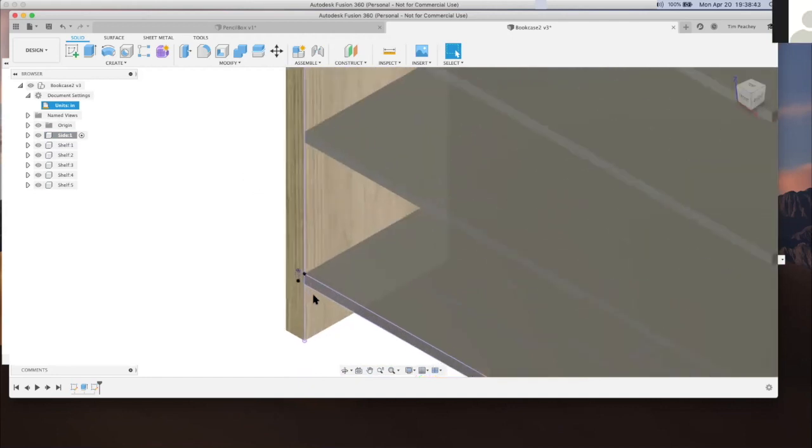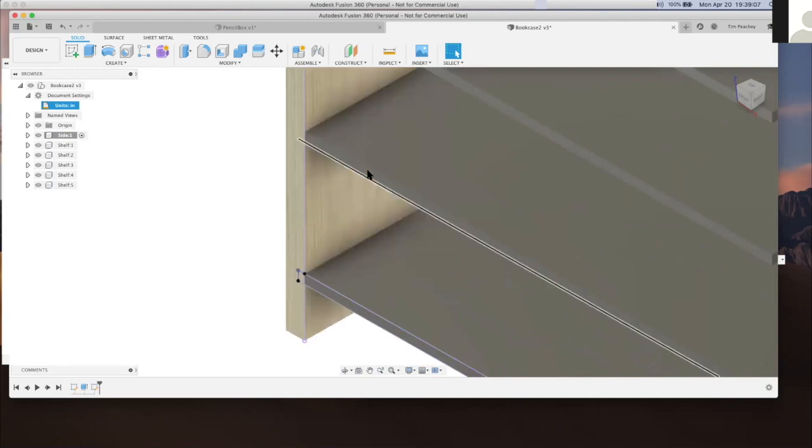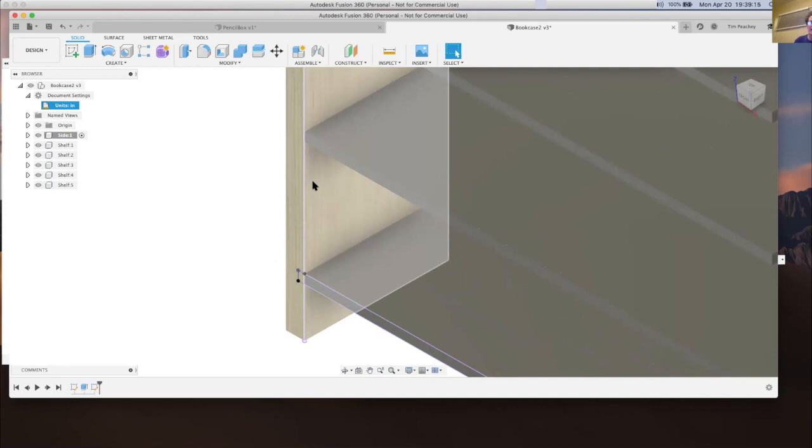Were not the shelves defined with their width plus 2 times the dado depth? That expression. Correct. So when you duplicated it 5 times and removed the top one, doesn't that automatically account for the dado depths on all the others? Yeah, they all have the dado depths, but the side panel doesn't actually have the dado cut into it.